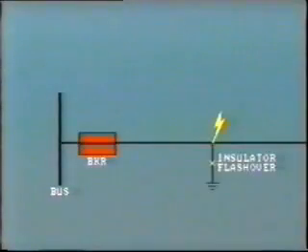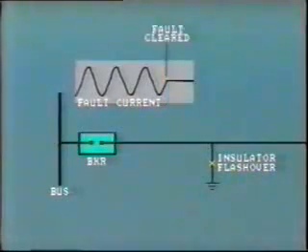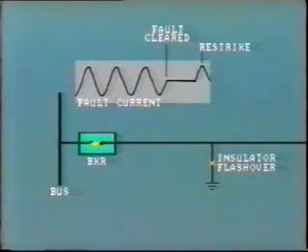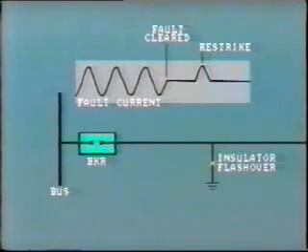Well, here's one way. A lightning strike to a phase conductor flashes over an insulator, causing a single line-to-ground fault. The breaker at the substation successfully clears the fault, but a very short time later, perhaps a few cycles, there is a second strike to the line. The resulting surge in voltage causes the open breaker contacts to restrike. But in only a few cycles, the ionized gases from the original fault have not had enough time to dissipate. So the original fault reestablishes itself. Usually the fault current will go out at the next current zero after a half cycle.